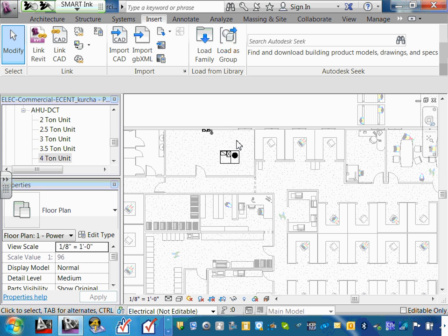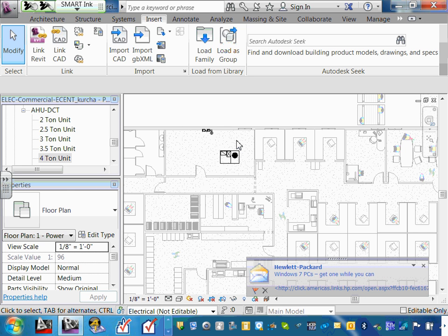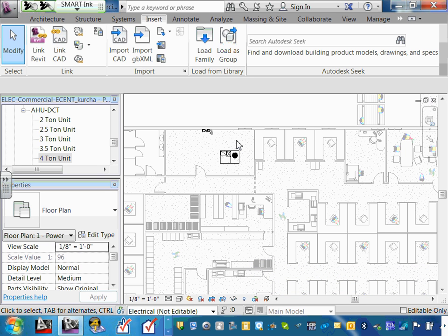The central model was saved in a different version of Revit. Close that one. And you know what we did for everybody? That's because of the full version. I will go create a central file for you according to save as project. We'll make a central file and we'll save the project there. So when you come here, see that the one says get the central file. Okay. This is your central file. No matter what, if you haven't done it, save it.